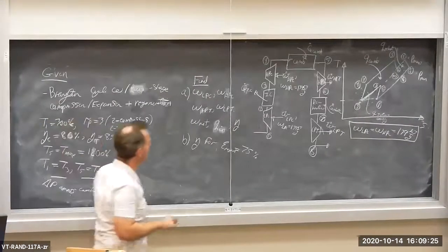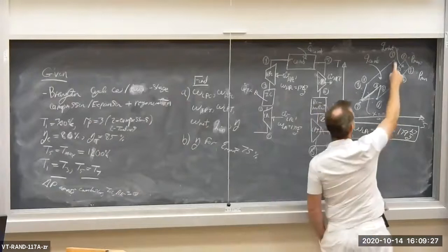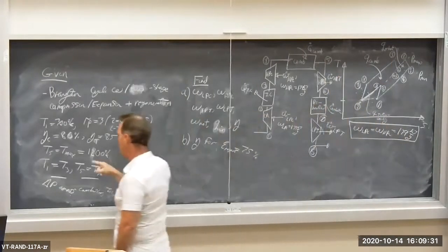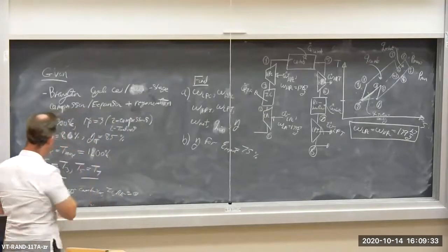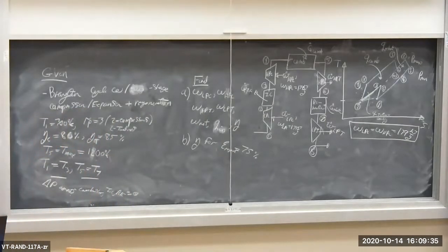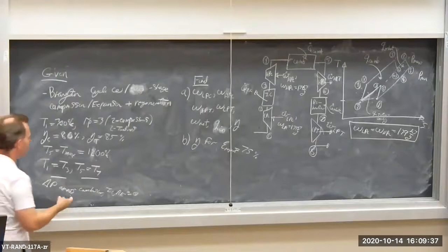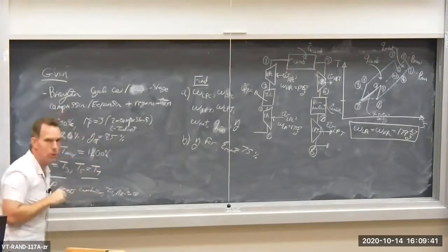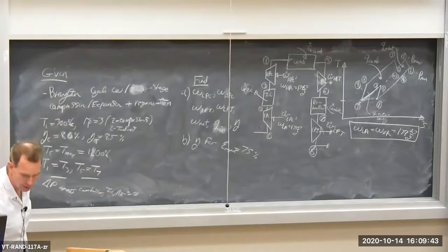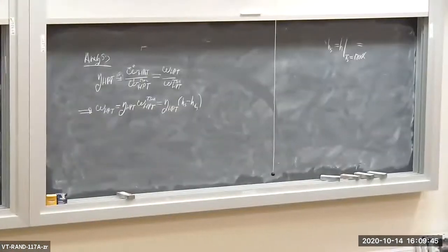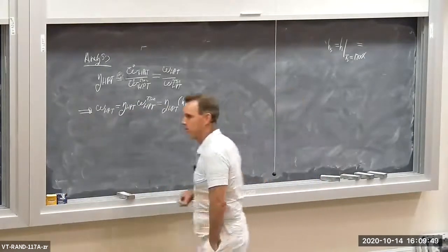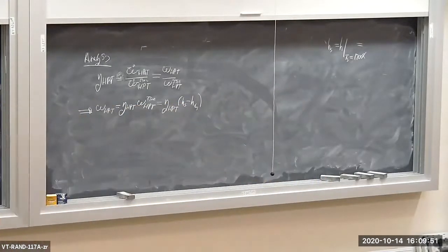So the maximum temperature of the cycle, the combustor exit temperature, that is 1200 degrees, T max, 1200 degrees, looks good. And by the way, before we get too excited here, remember these turbines and compressors, each individually has a pressure ratio of 3. Just a reminder here, because we're going to use that in a moment. Okay, so I know H5. Let me get H5 evaluated at 1200 degrees.